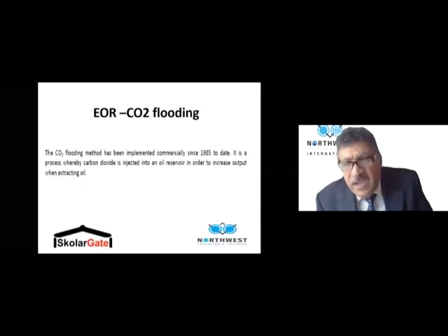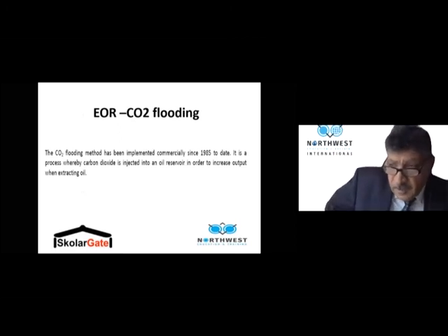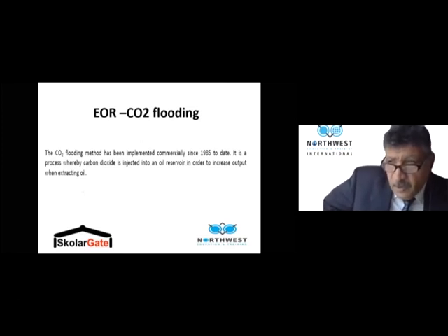CO2 nowadays, people talk about CO2 as a good technique for enhanced recovery, tertiary recovery. CO2 comes under the tertiary recovery. And CO2 comes under miscible or sometimes immiscible, both. If CO2 mixes with oil and dissolves inside oil, we call it miscible because it has enough pressure to be mixed. If CO2 does not dissolve in the oil, we call it immiscible.